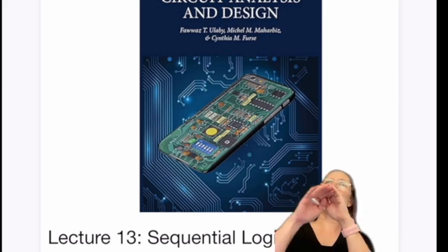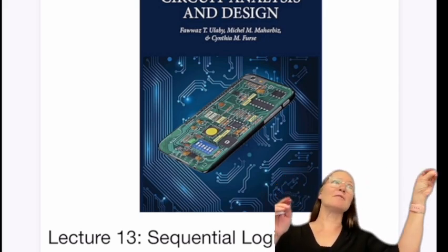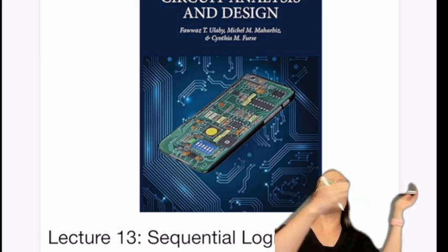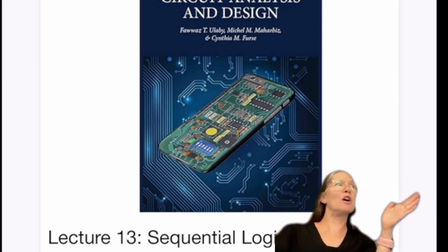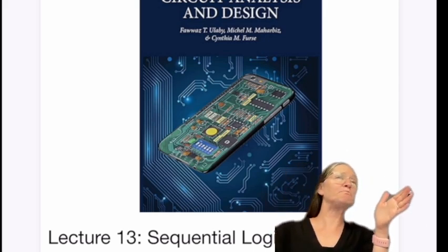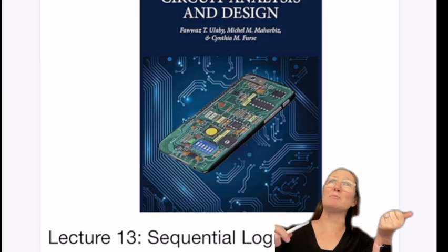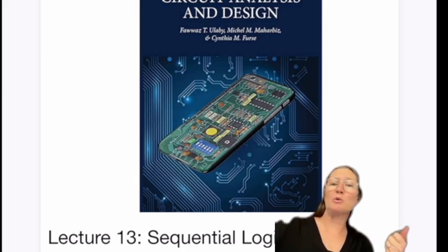So 3 flip-flops were in that one, and they were your memory elements to differentiate between combinational logic, which was very straightforward: if I have 0 and 1 as my input, then I get this out. If I have 1, 1, this output, and so on. So those are not having a memory element. The difference between the sequential and the combinational is that memory element.